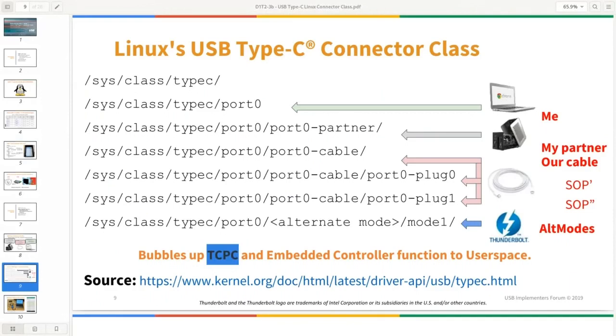Get a full-featured cable, USB 2 only. Correct. Yeah. Actually, I've presented the USB 2 cables and the full-featured cables. These are the ones which are specified. You have lots of things in between. I found cables, for example, magnetic cables, which don't allow power delivery to go through because they do their things themselves. They don't allow shields, so you have plenty of things in between.